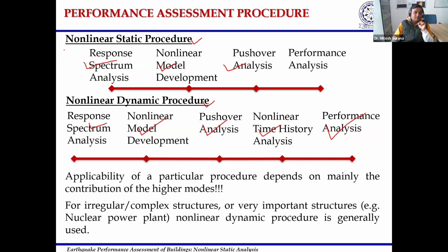Now, whether we perform nonlinear static analysis or nonlinear dynamic analysis depends on the contribution of higher modes. If the contribution of higher modes is not significant, then nonlinear static analysis could give you good enough results. If the contribution of higher modes is significant, in that case you need to go for nonlinear dynamic analysis as well. So if we are analyzing a complex or irregular structure or a very important structure, in those cases it is preferable to always conduct nonlinear dynamic analysis also.